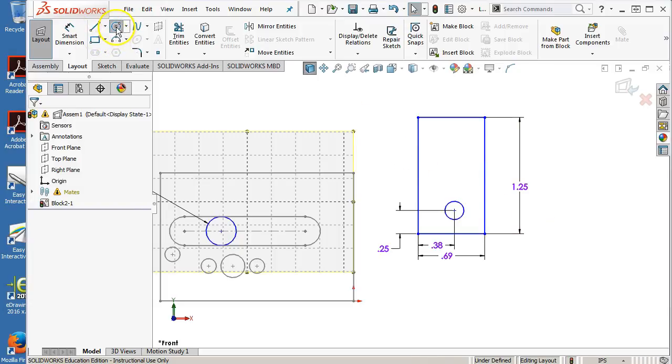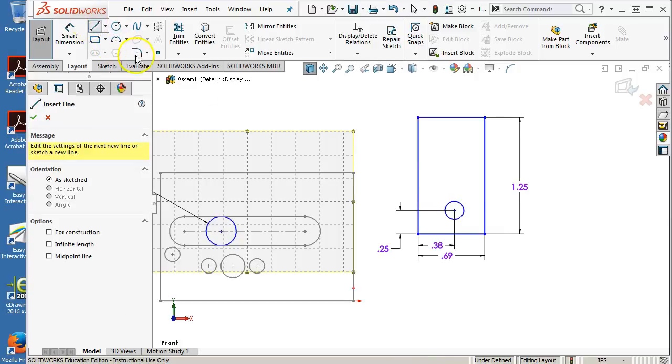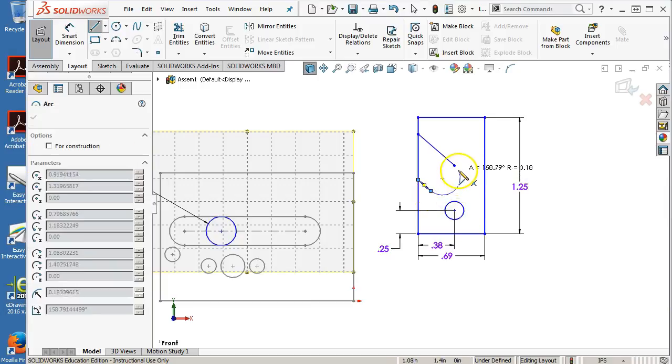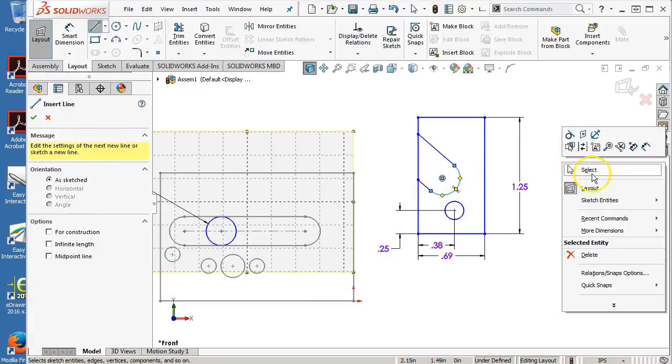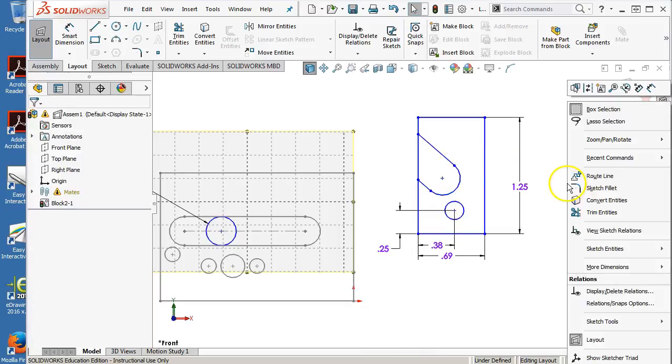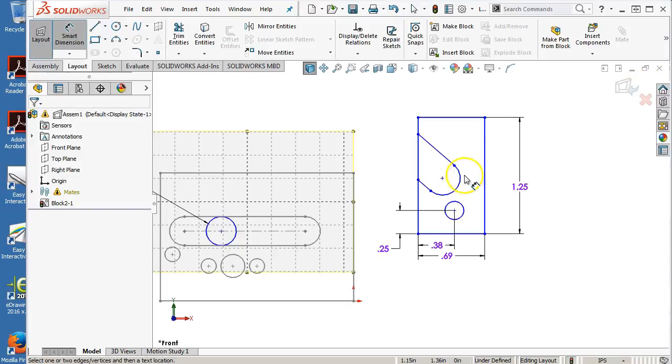So for the arc then, let's go ahead, and this is going to come down at some angle. This is going to be parallel. And then I'll do the continuous to generate the tangent arc. It did go to tangency there, so that's okay. We had a radius of 0.188.